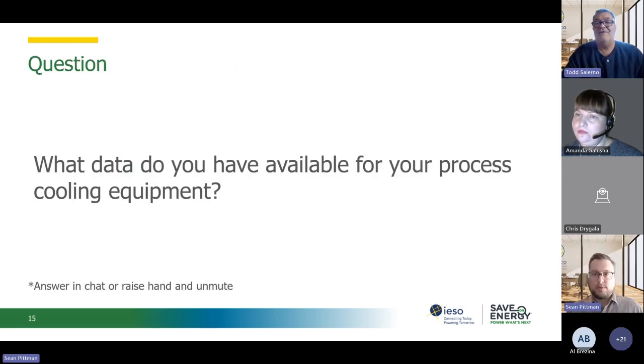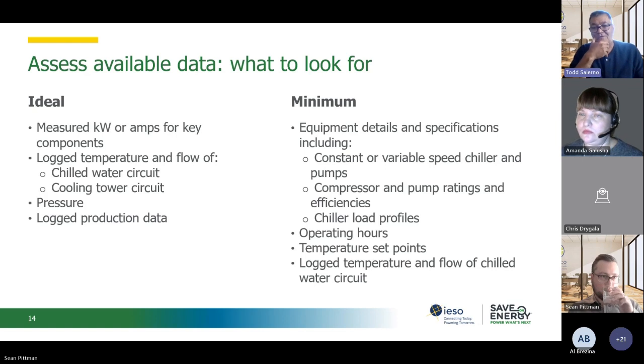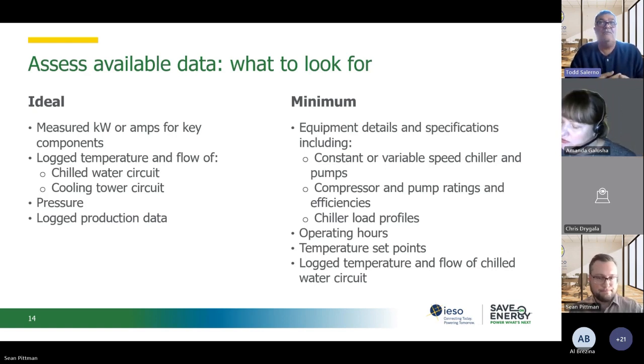I was going to add something on that too. There are a lot of small things you can pick up. For example, I've run into situations where you're looking at a system and I notice that they've used isolation valves to throttle the flow to certain areas. Those things should also be noted. Equipment condition too: you could have pumps with leaking seals or making a lot of noise that may also need to be replaced as part of the retrofit.